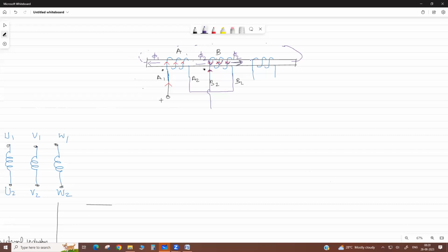Okay. So in the case of a motor, there are 3 coils A, B, C. That is why, if we connect them in star or delta, their polarity is very important, so that their fluxes aid. Then we get a resultant flux of constant value. Same as in a transformer.